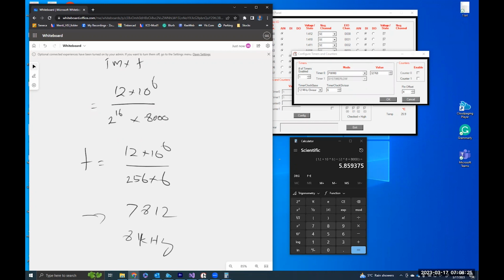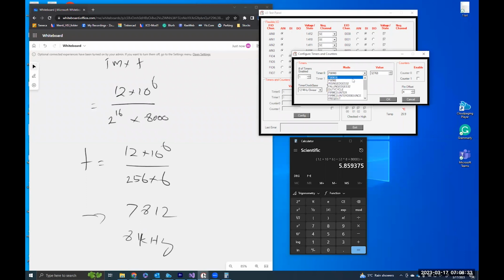So the takeaway here is that the divisor, or not just the divisor, the PWM mode that we have here, and the multiple divisors that we have here, all help us to find the sweet spot, right? Whatever number we want, we can achieve by changing any numbers here to get the frequency. In this example, we looked at 8 kilohertz here.